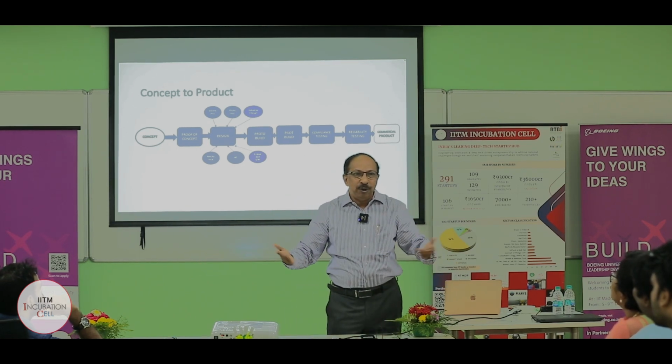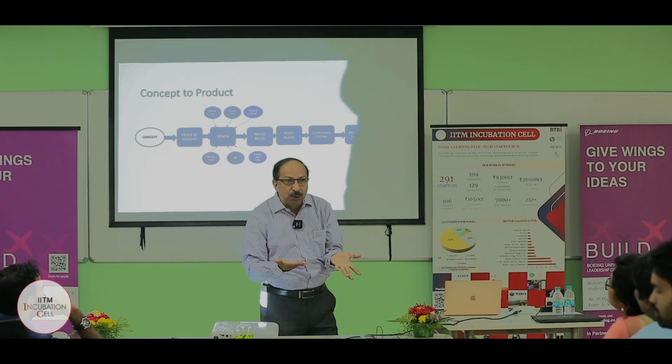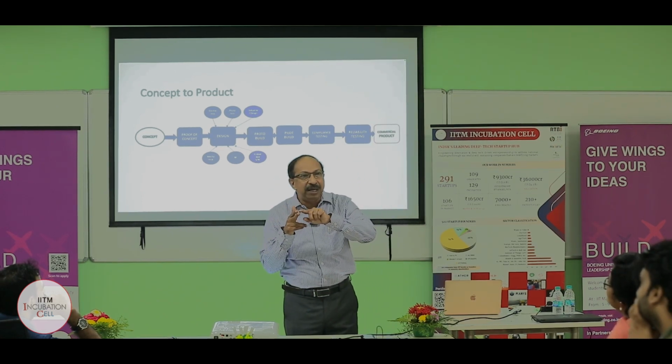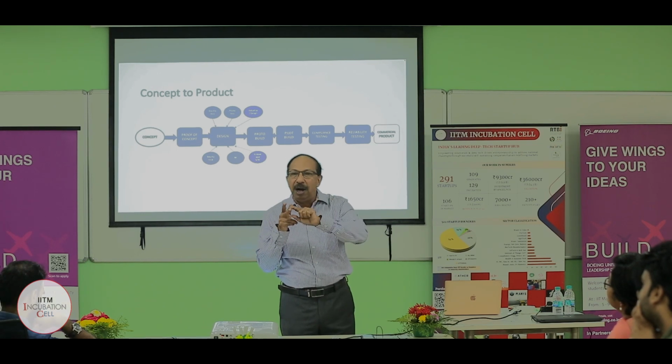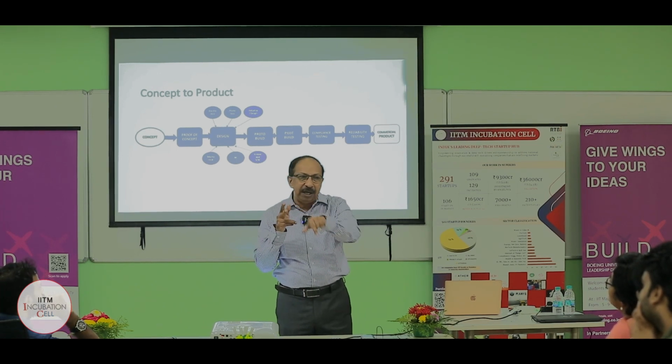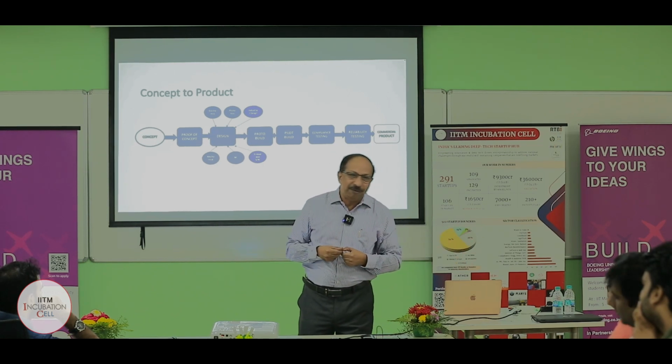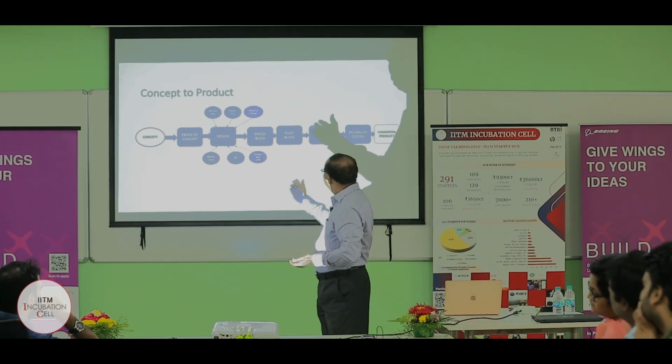That's all. So if you have thought of this when you do the design, what you can do is, when electrostatic discharge comes, you put a small ESD diode, which will take it to ground. Okay, so that your product will survive. So these things you have to think about.